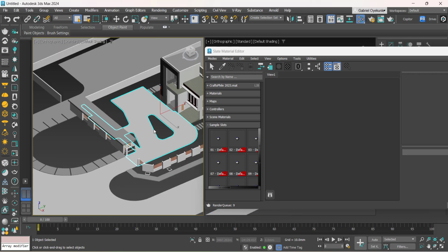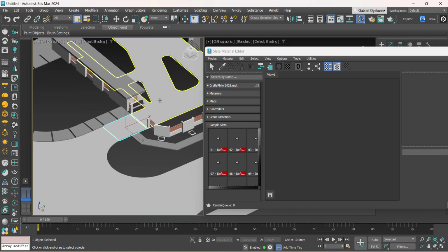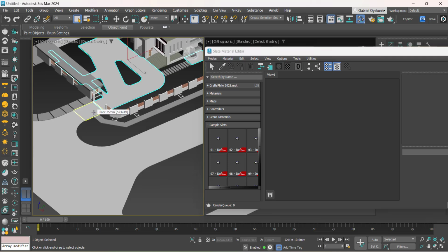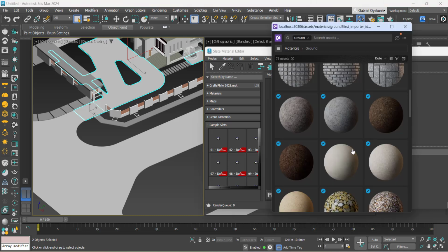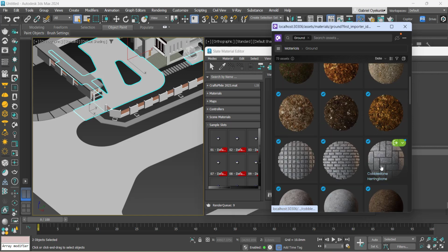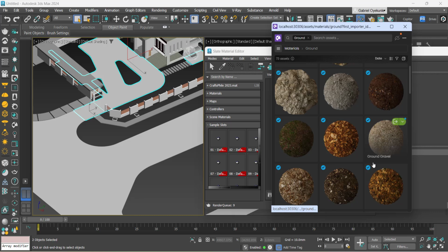This is supposed to be interlocks, and unfortunately when it was done in Revit, it was the same material that was on there. So what am I going to do in that case? I'm going to select this and press Ctrl to select the second one, and I can maybe use this, or let's see if there's any other one. I think I prefer this.